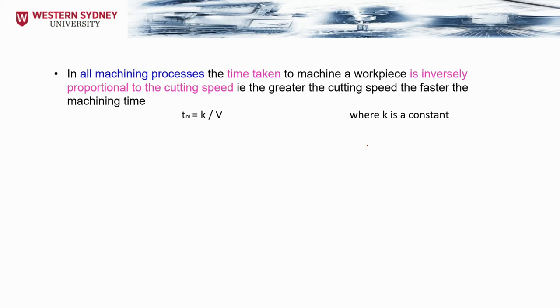Reducing the tool life is going to increase the cost of the tool, which is another parameter in the cost of the machining. So in that case, you say, okay, now let's go for lower speed. Now this will increase the time of the machining, and thus we are going to have an extra cost for the machining. So both statements are not going to be correct, and the best option is simply to find the optimum speed of the cutting.